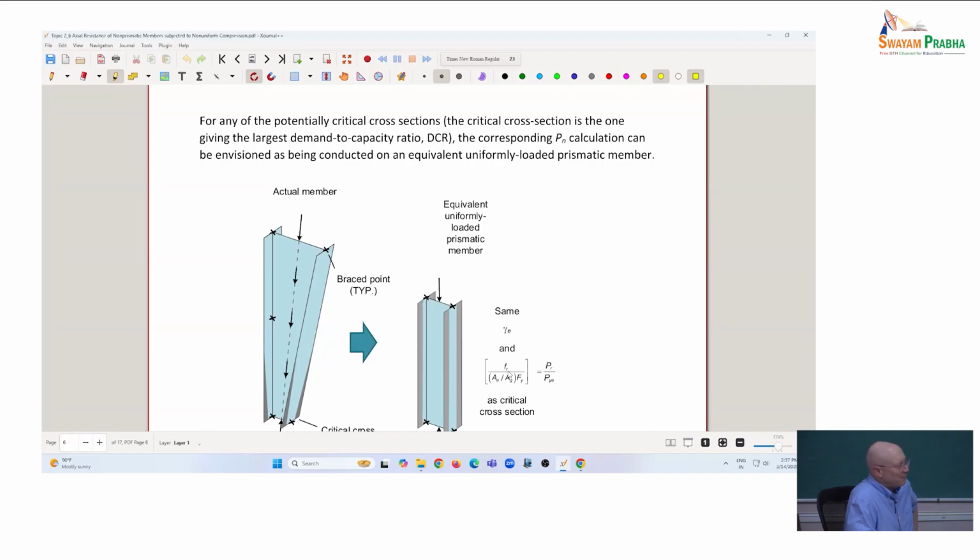If you can identify where that's largest, then zero in on that cross-section, just do the cross-section, and do the calculation there. In general, the way the equations work in the AISC standard, you may have a slightly larger value at another location, but the difference is going to tend to be very small. For using the Eurocode approach, or I believe it would be true also in the Indian standard, where you